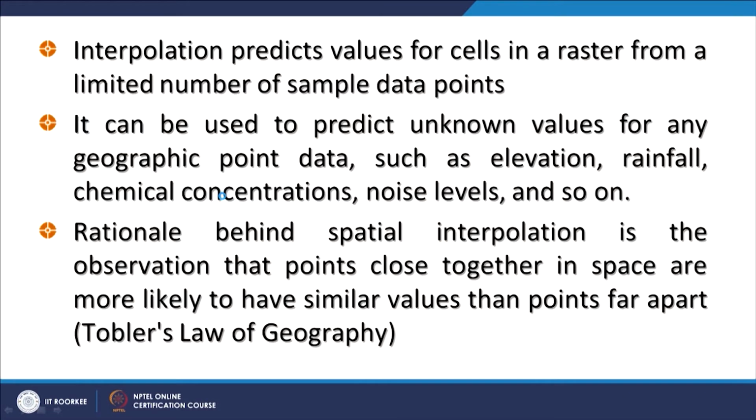Second, the purpose or rationale behind spatial interpolation is the observation that points close in space are more likely to have similar values than points far apart. And this Tobler's law of geography is employed extensively in spatial interpolation, because a point which is very close to an observation will have more influence while doing the prediction than a point or cell which is very far.